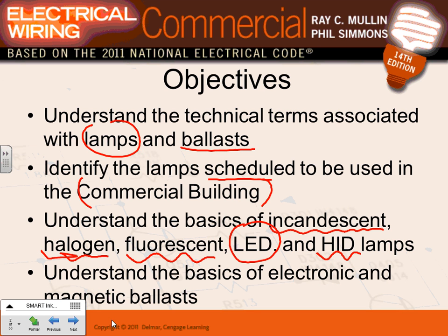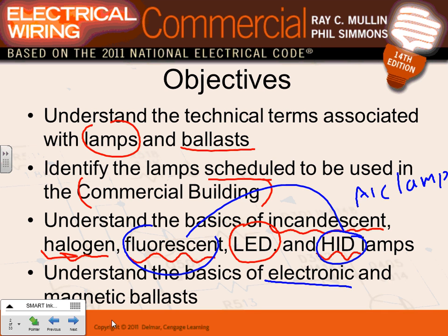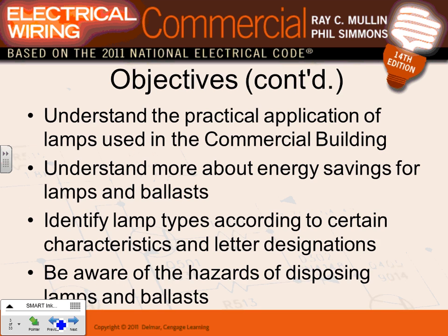I don't know if you remember when we talked about these different types of lamps, we said these two lamps are called arc lamps, right? Because they require an arc. And every time you have an arc, Jeff, what do you need? You need a ballast, electronic or electromagnetic ballast. So that's why we have to talk a little bit about electronic and electromagnetic ballasts. Any comments, guys, about the different types of lamps and the ones that need electronic or electromagnetic ballasts, the arc lamps?